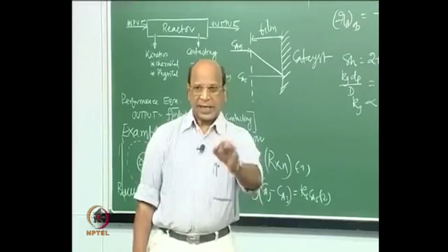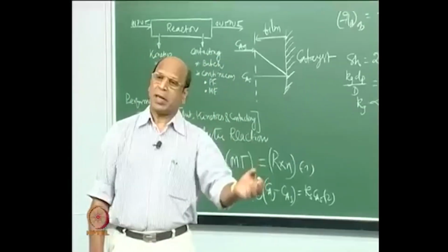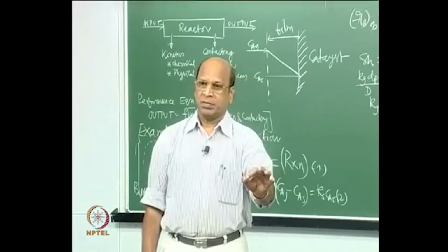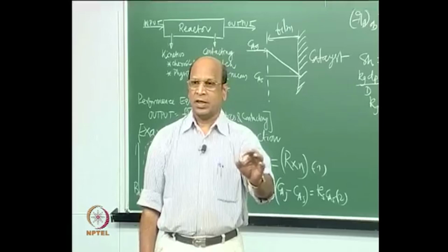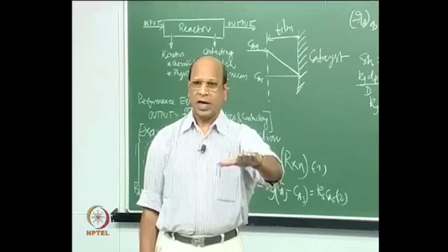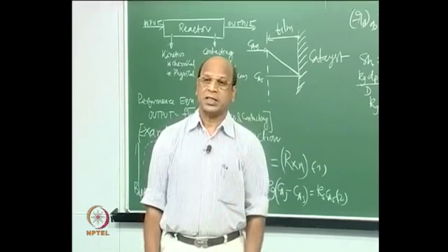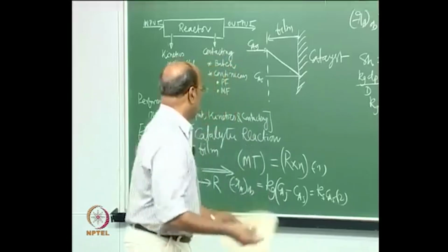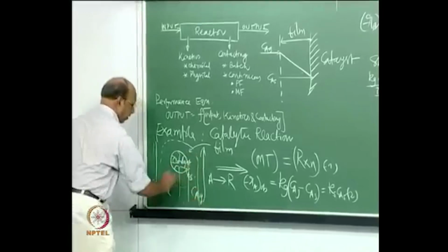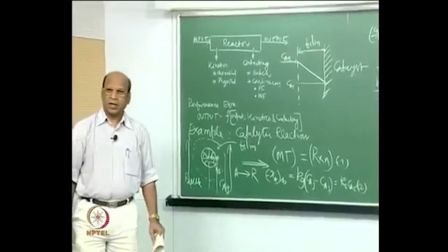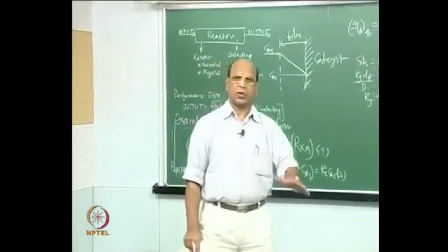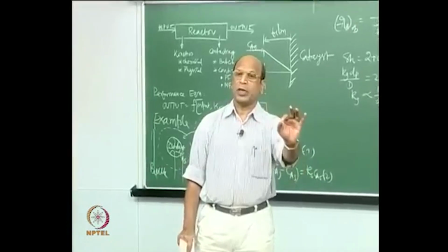It is a packed bed, so that means the packing inside is a solid. Can I also imagine how the concentration varies inside the particle, and how the concentration varies between the particles, because it is not uniform everywhere, and also how the temperature is changing? So, if I have a single particle like this, can I draw the concentration and temperature profiles across all these? If you are able to imagine all that in your mind, then automatically I tell you that you have a clear picture of what is to be expected mathematically.